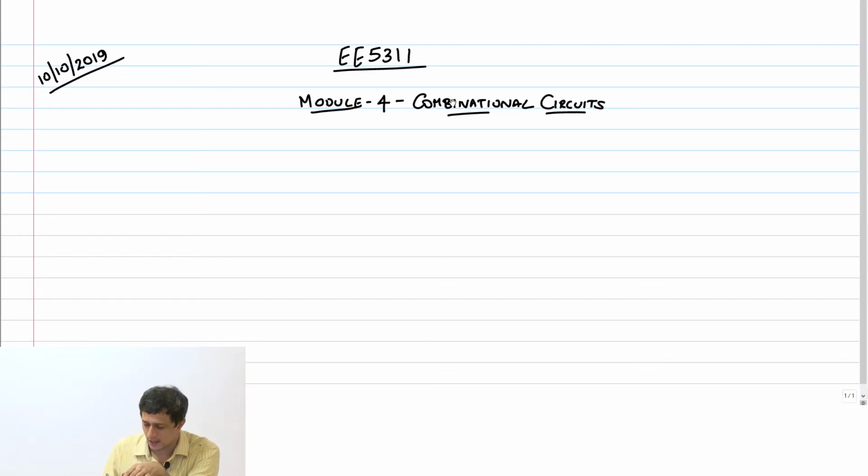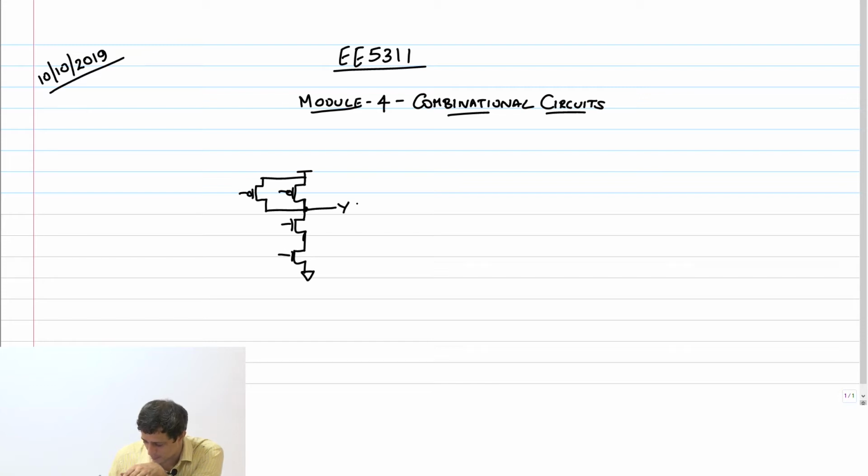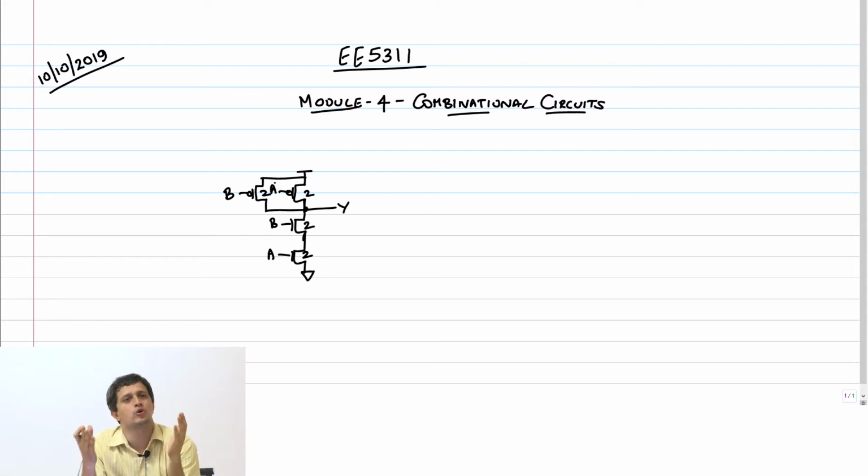Okay. So before I reduce the logical effort, let me also deal with another important concept. Suppose I have a NAND gate here. A, B, and A and B, right? So size is 2, 2, 2 and 2. Okay. Now my question is, logically, these two inputs are identical.